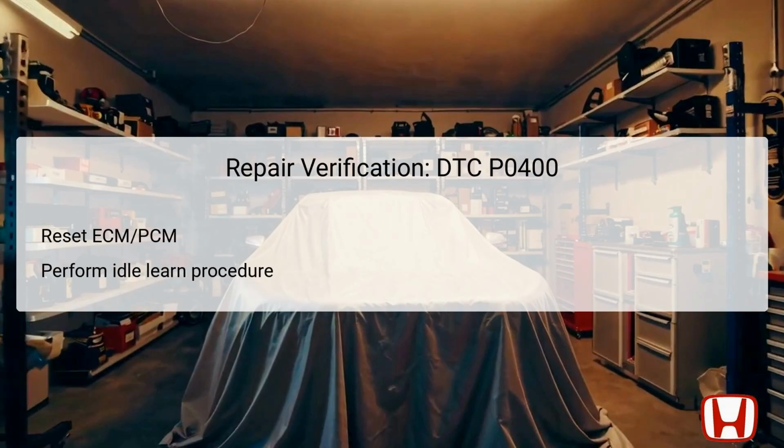After addressing the issues within the EGR system, a thorough repair verification step is essential. Begin by turning the ignition switch to the on position to initiate the reset of the engine control module, ECM, or powertrain control module, PCM, using the HDS. This action clears any stored fault codes related to DTC P0400 and allows the system to refresh its parameters.